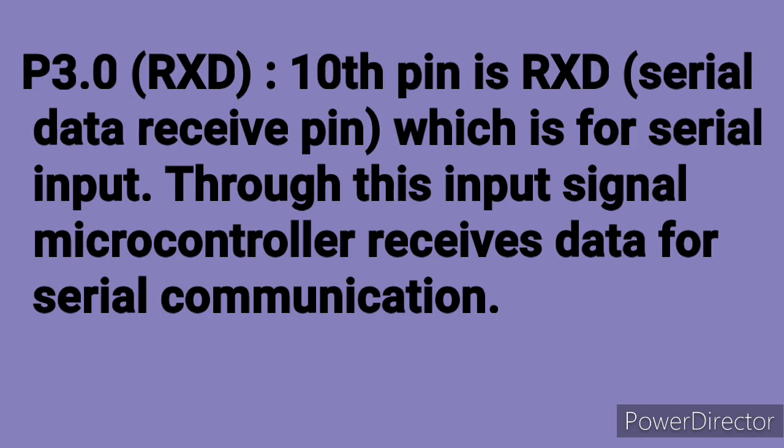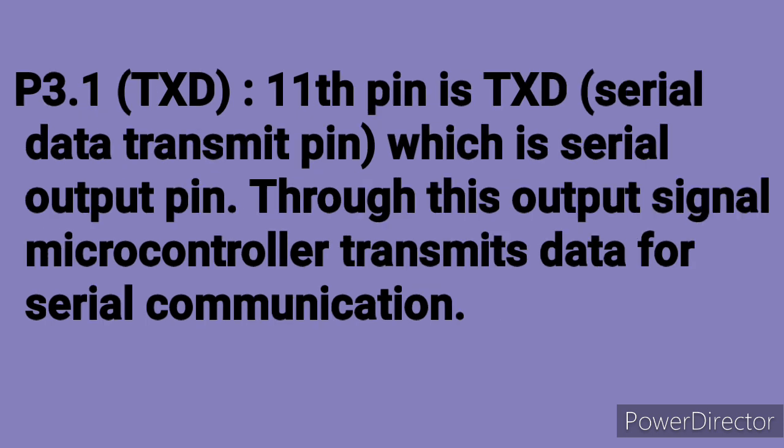P3.0, 10th pin, is RxD, serial data receive pin, which is for serial input. Through this input signal, microcontroller receives data for serial communication. P3.1, 11th pin, is TXD, serial data transmit pin, which is serial output pin. Through this output signal, microcontroller transmits data for serial communication.